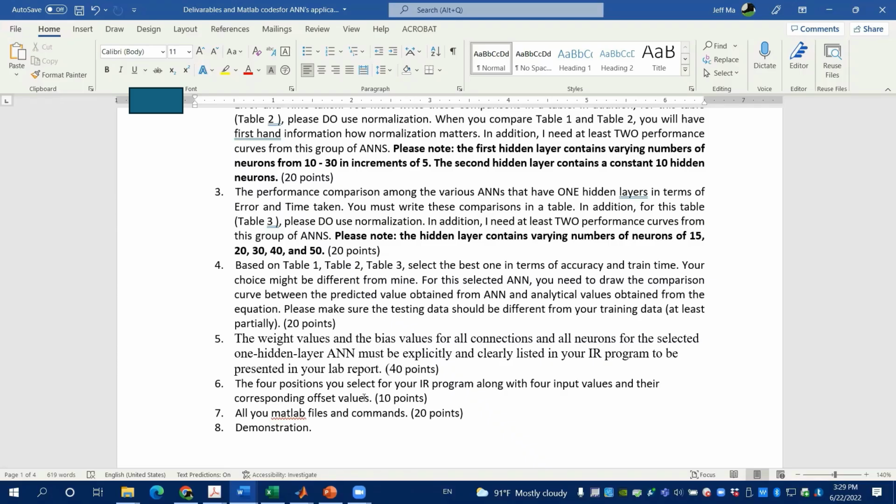This means that when the hand moves, the actual trajectory, the actual path of your hand, will not be the desired path because of the pushing back from the workpiece. So in this case, how can we offset and compensate for this?